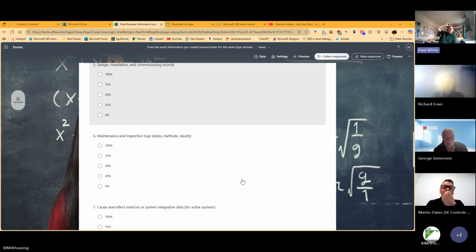Sorry, George. So if you take a smoke control system and you look at BS 9999 and 9991, it says you should be checking the smoke control system every day. That's the panel, looking for faults, which I keep telling people is a bit of a waste of time, because if it hasn't gone into alarm, you won't see any faults because everything's in the place it should be. But you should in theory be checking the physical assets every week, or a proportion of them, and I don't think I've ever seen a record of that. And that's really the point.